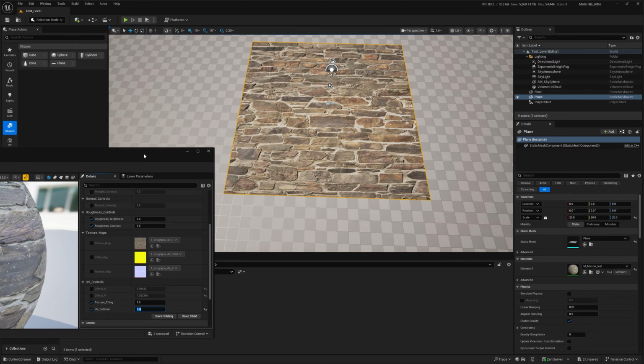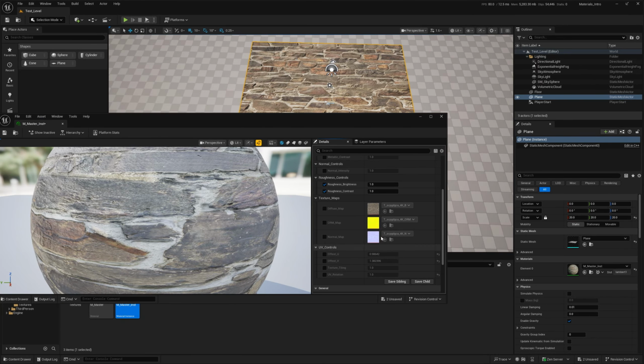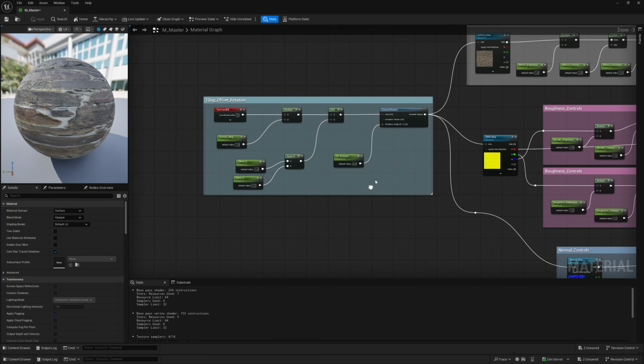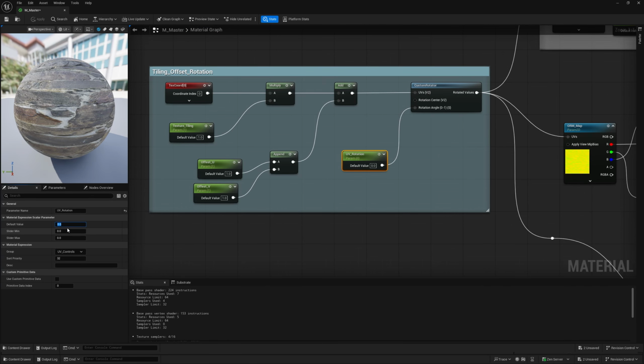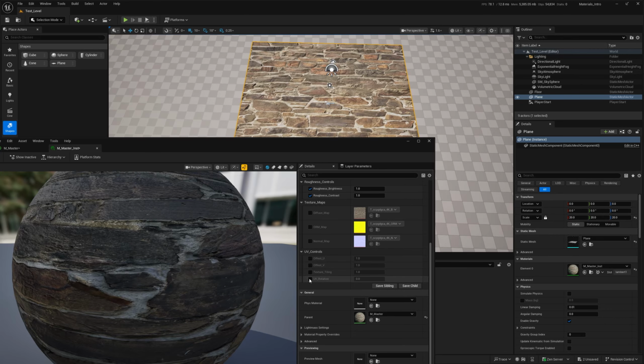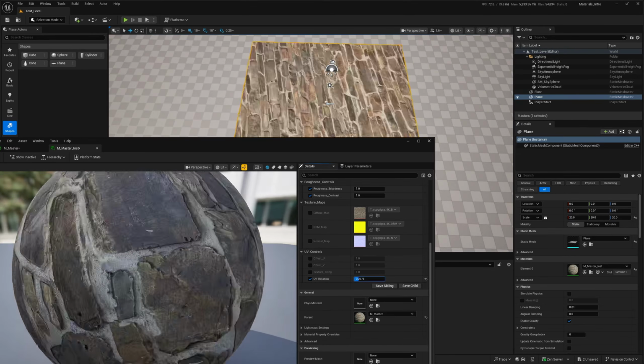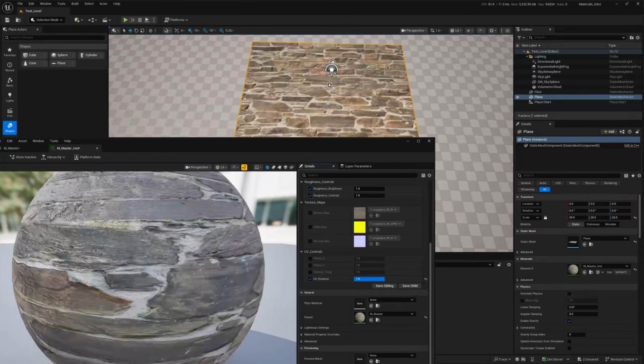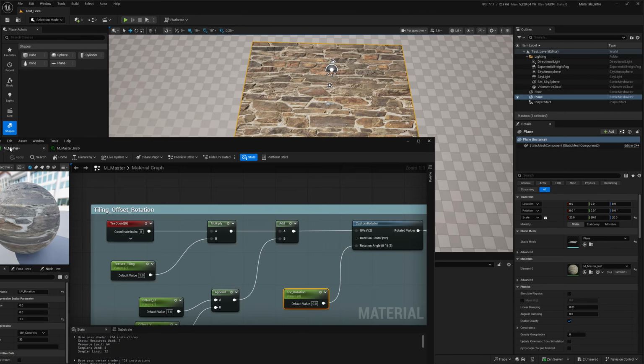Okay, so you can limit the sliders, for example, if you want them to be between specific values, like this rotation, so it will not go over these values. So you can put the min, the default, and max here, so it will not exceed this value. So if I go now and try to push the rotation over 1, I can't. So the maximum is 1. So that's a way to limit these sliders.